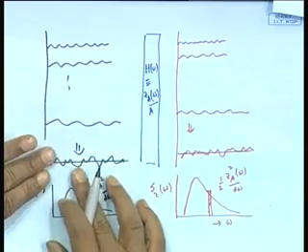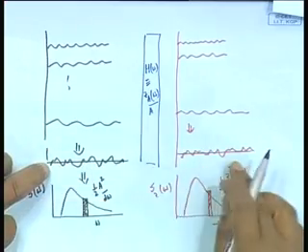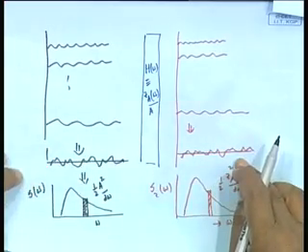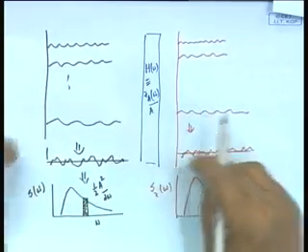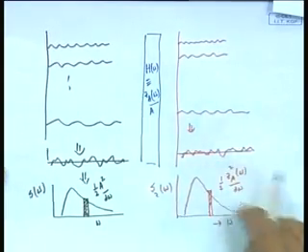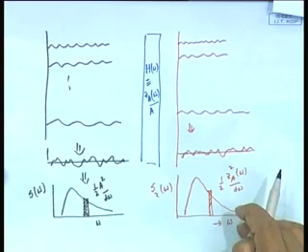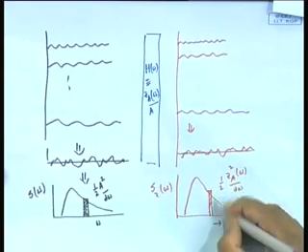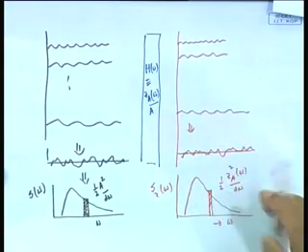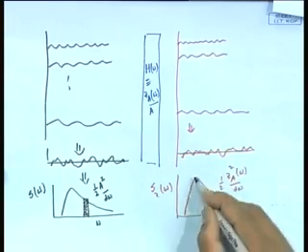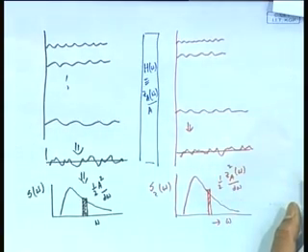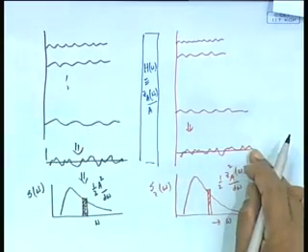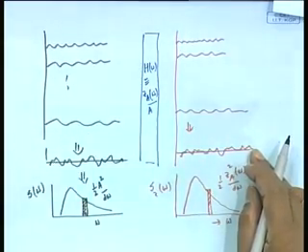Let us say this black line is, I just drew this black line in a red pen. So, I have this, instead of eta I have here z with an amplitude ZA, instead of A I have ZA. So, I have exactly the same spectrum. In other words, what does it mean? It will imply obviously half of ZA square by omega. If I add this area up, I will end up getting essentially a quantity proportional to energy of this spectrum into rho g, because energy of any signal is proportional to half of amplitude square.